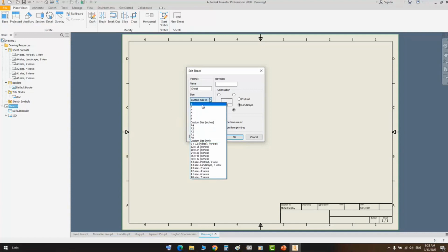And here are some other standard sizes in inch values. So the value here, which is 8.5, will be defined in inches. Those are the English sizes. Let's select the A2 size drawing. On the second part on the right-hand side, you can define the revision number of this sheet, so you can add it as revision 0, revision 1, and so on. And from here, you can change the title block location. You can make it on the bottom right side or bottom left side.